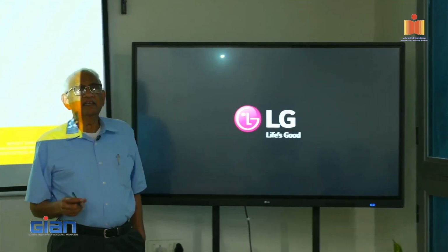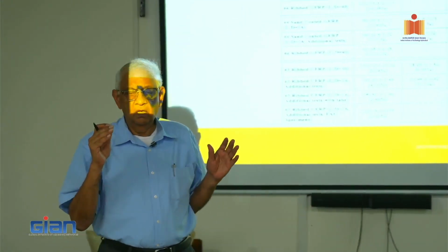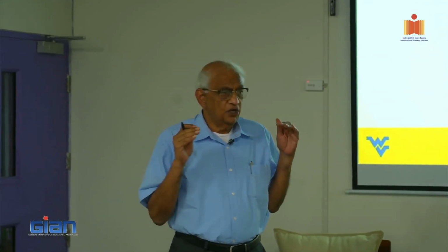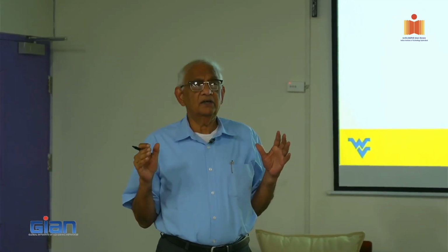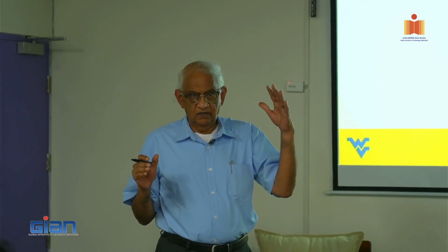The nonlinearity comes, this is what we call a geometrically nonlinear response. You know the equation, d square y over dx square is equal to Mx over EI. So on the left side, you have really another term, a product term, which is 1 plus dy over dx whole squared, to the power 3/2.